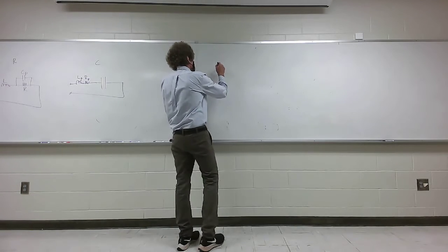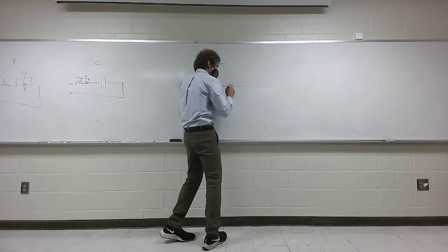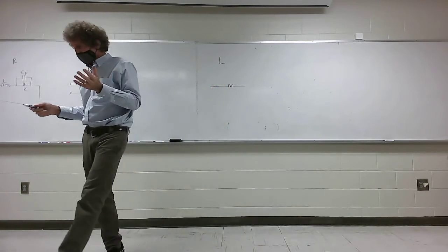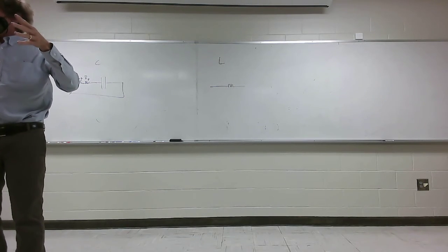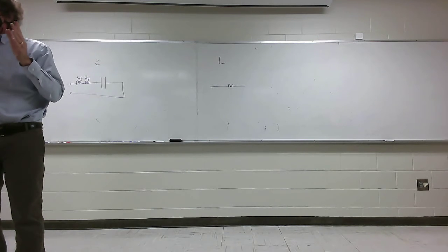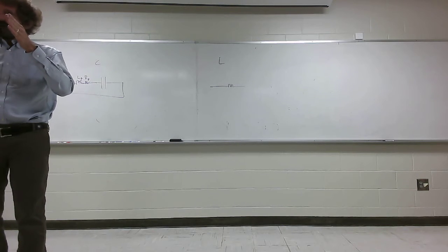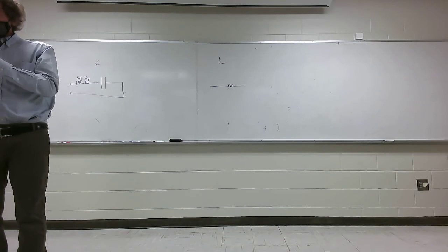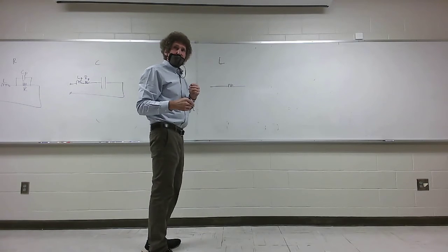Finally, for an inductor, this will be the high frequency model for an inductor. You always start with an inductor. When you think of inductors, I always think about a lot of wire that's wound close together. Now, the truth is they don't have to be wound on a core. If you have a serpentine system like this, it will have inductance too. There's a lot of ways where you get self-inductance of a line. You don't have to coil, but coils are the most common.